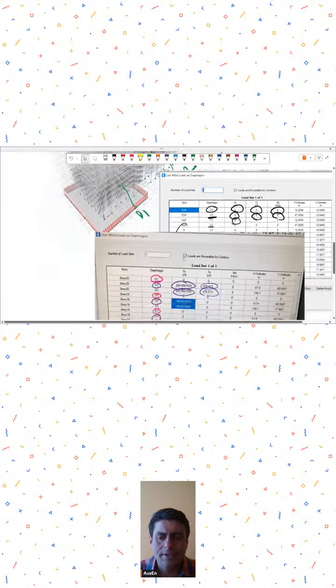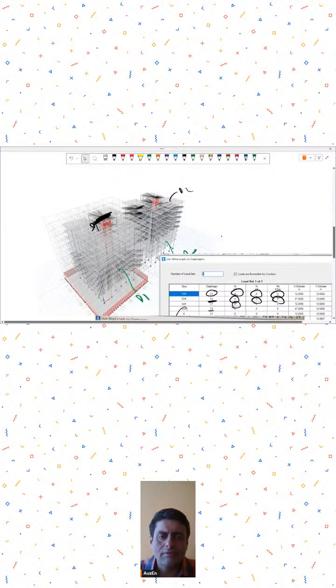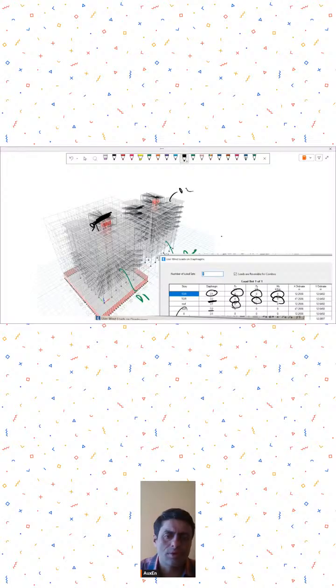And then these wind forces, either you can calculate manually, wind or earthquake, whatever, or you can take these from some gust factor sheet, or let's say from internal testing, and then you can put them over here in this way. Is it clear? Yeah, so what you have done, I was also trying to explain the same thing. So assign diaphragms, and no need to assign different diaphragms to different floors in one tower.